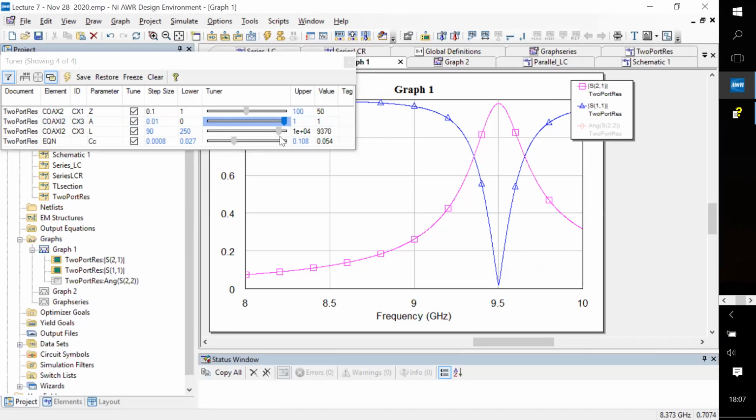So the introduction of the loss in the central part of the circuit also makes the system somewhat asymmetric, and it doesn't allow you to get this perfect interference. So you don't have unit or zero reflection on resonance when you have a case like this.